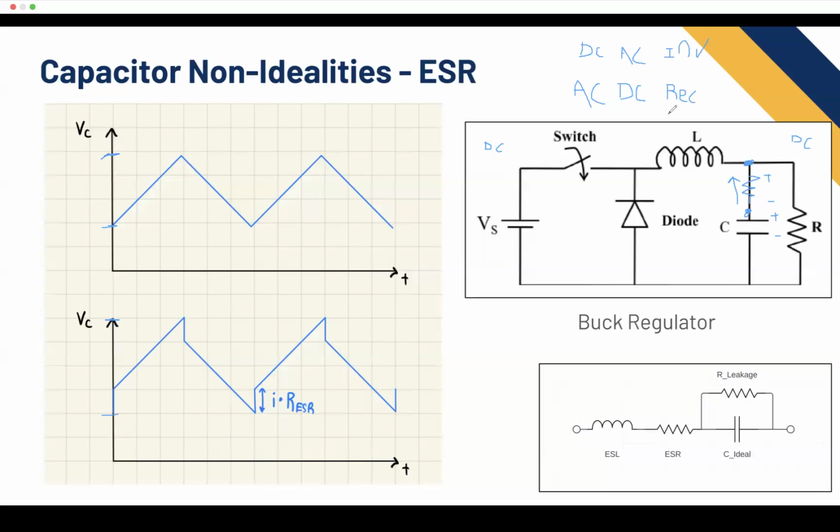But anyway, the way this works is basically, let's say in the first state, the switch is closed. You're going to have current going through here. Then you have a reverse bias on this diode, so this diode's basically like an open switch right now because we have this voltage source across it.